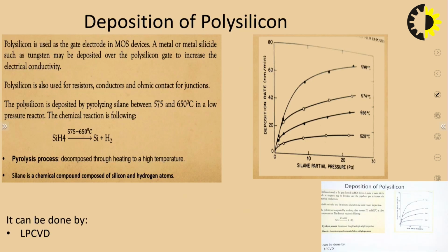So first of all, deposition of polysilicon. Polysilicon is basically used in most devices. It can be used for transistors just to create, you can say, the ohmic contacts. So such polysilicon deposition is quite important. This polysilicon deposition is done by the APCVD method.